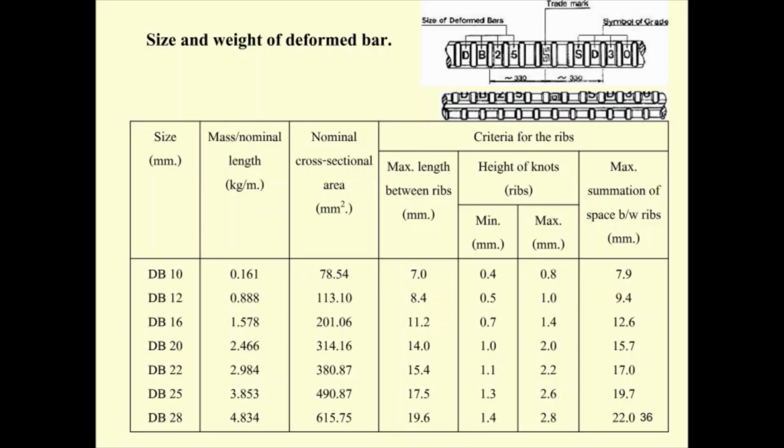Okay, you may say you have this size, and then you got to check what you have for your cross section, and you must follow it. And again, the rebar is going to have the DB here, and also the size here. Okay, this is the company that produces it, and this is the grade. It may be SD30. Now there is SD40. SD30 is the old standard. And now the popular one is SD40. And the new one is going to be SD50.